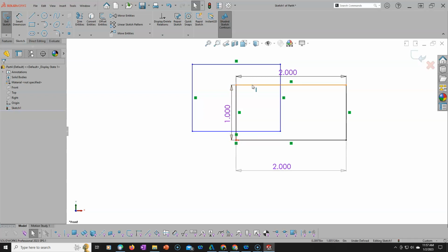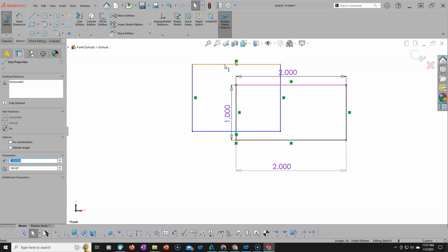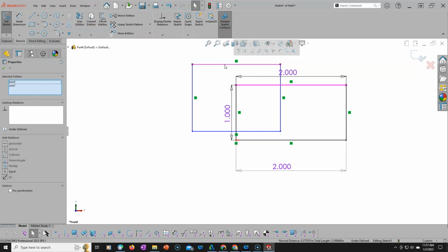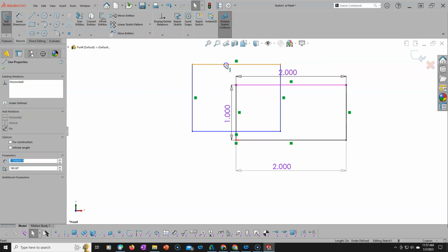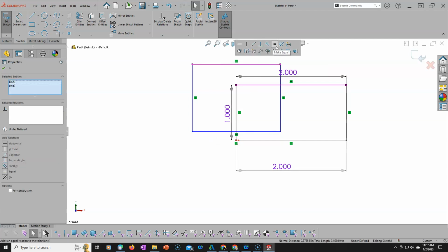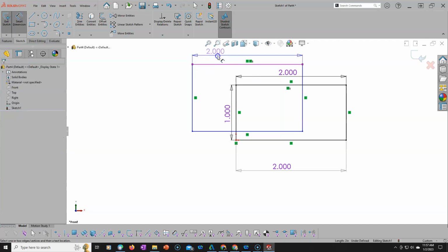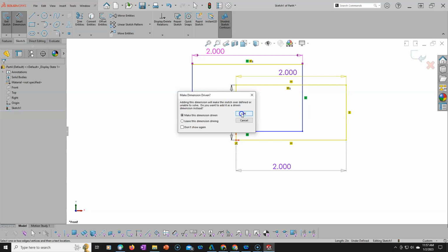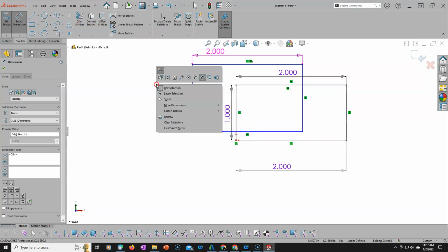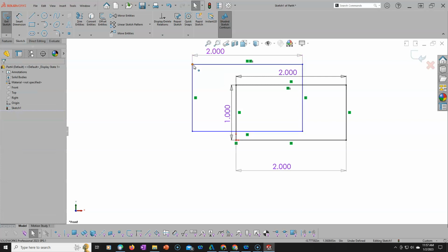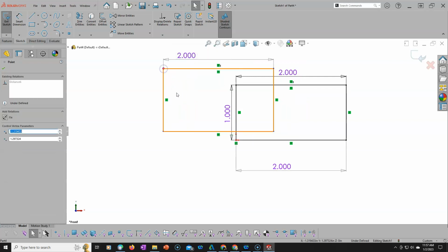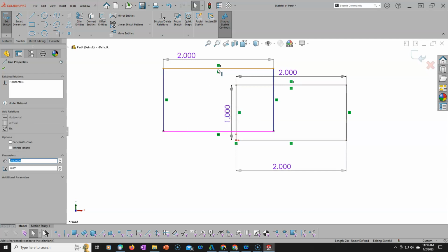So if I set that line, and I'm going to do the famous select, control select, I've only said that a couple thousand times. Hold down, select the first object, hold down the control button, select the second object, and we'll have up here somewhere a make equal. If I've made those equal and then I try to add a relation, it's going to give me the same thing. It says the equal relation is priority there because it was applied first. All right, so the 2 inches isn't going to help. And because vertical, vertical, then that would also be 2 inches, even though I applied the equal.